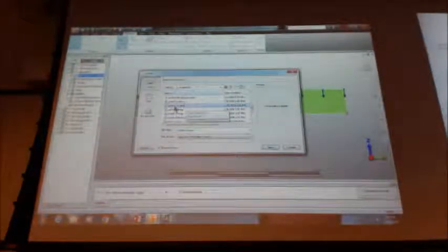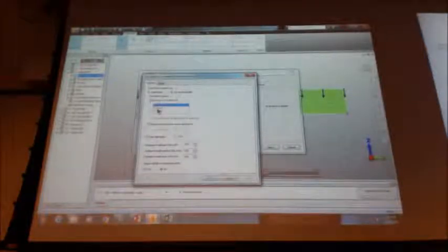But before you pull it in, you have to go to this Options button down here and make some selections. So all the drawings are 2D, and they were done in the XY plane, but you want to transform it to the YZ plane, because the Autodesk product only does 2D in the YZ plane. Don't ask me why, because I don't know. And you want to import the lines as arcs, curves, as mesh lines, so that you can mesh them. Okay, and the arc divisions is fine. You can leave everything else.